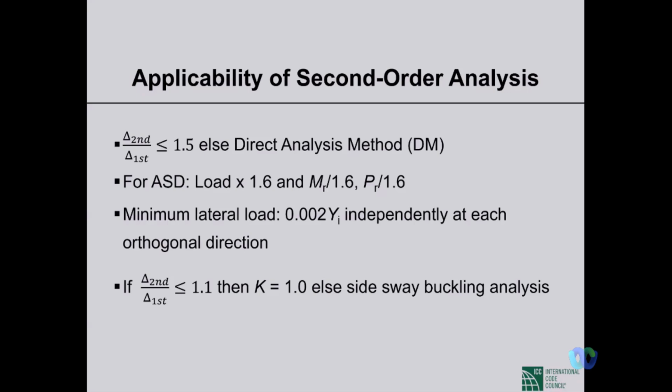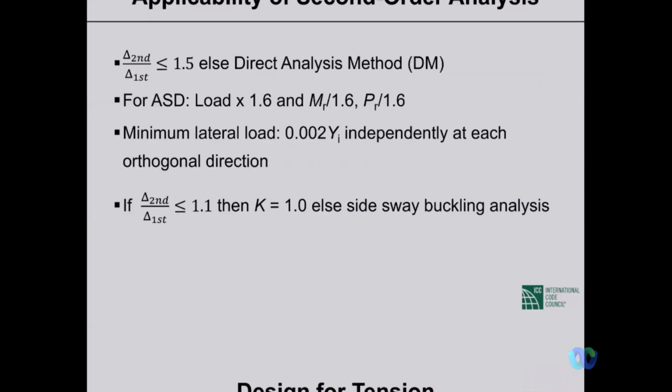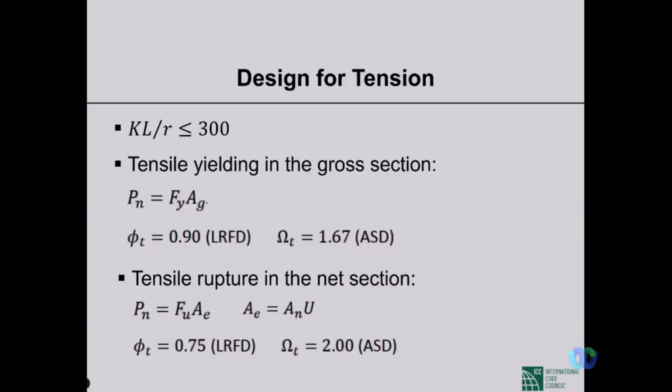That means simply supported, right? But we know that there are rigidities, so K should be less than 1. But this is very conservative if we take K equal to 1. In many cases, we actually are very conservative. We take K as 1. Now,